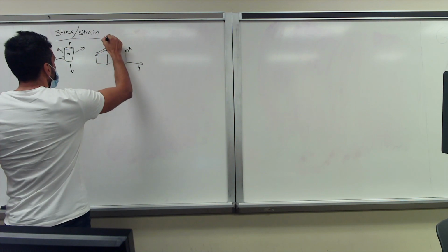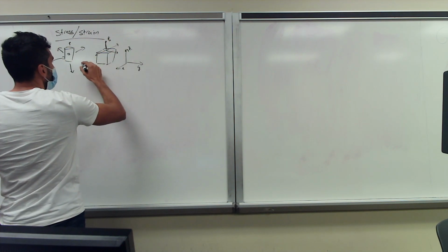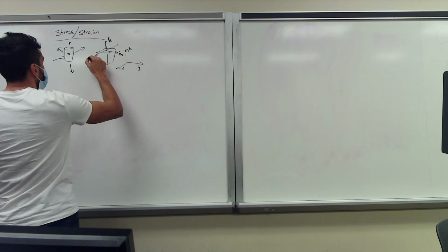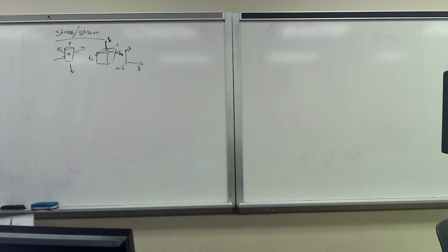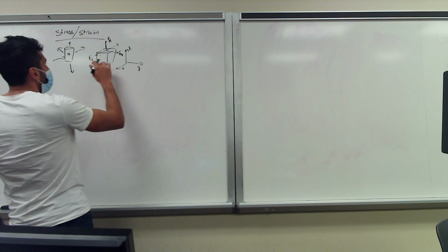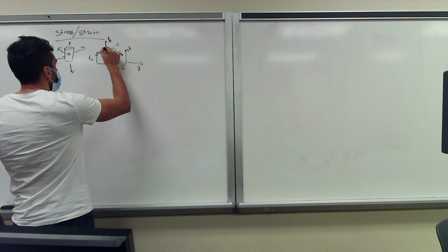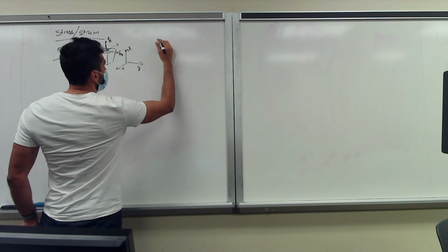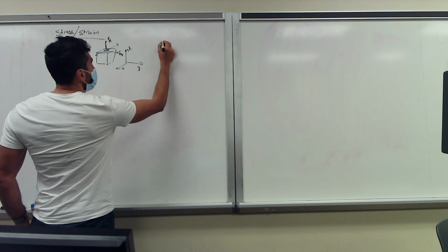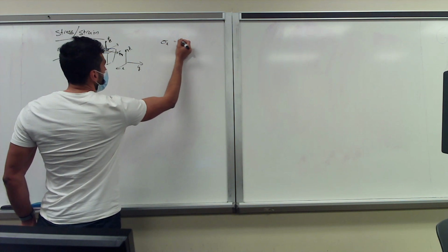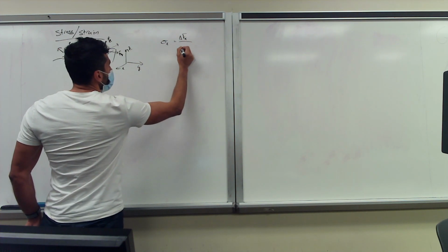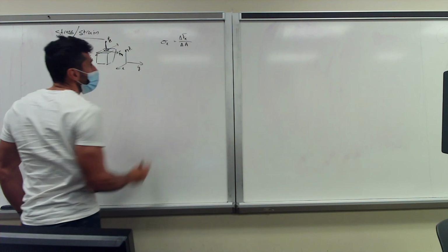If I look at the force here, Fx, and I will see Fy and Fx. I'm normalizing with respect to my area, which is x. So this is a small incremental area. Then I can get my corresponding intensity, what we call sigma x, in this case stress x. So that will be your delta Fx over the small area A.